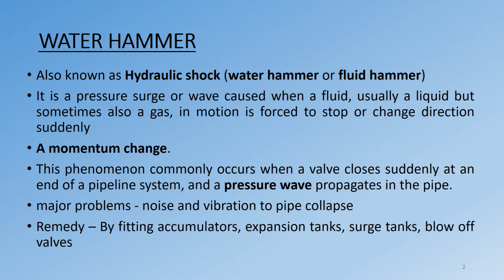This sudden momentum change creates a pressure wave. So this commonly occurs when a valve closes suddenly at the end of a pipeline and a pressure wave propagates in the pipe. This pressure wave can be so intense that it can create noise and vibration, and ultimately it can lead to collapse of the pipe. So this vibrating sound or a ringing sound or a hammering sound is commonly referred to as water hammer. So it is a harmful effect or a bad effect.